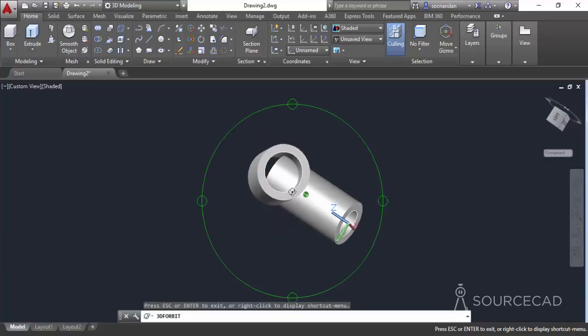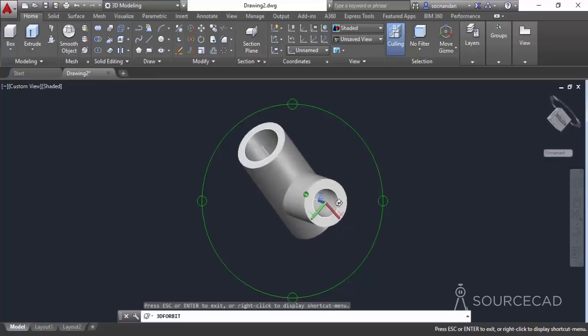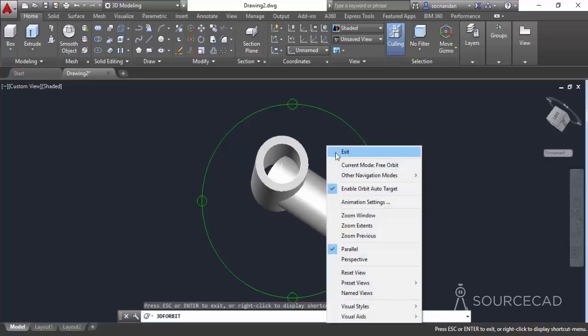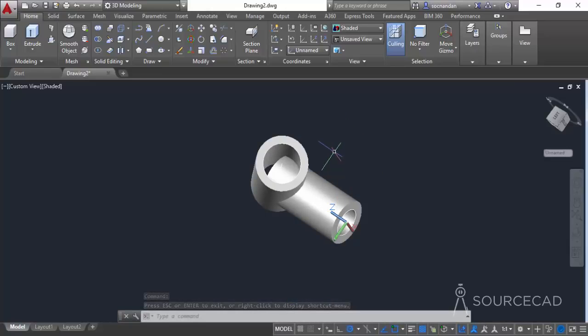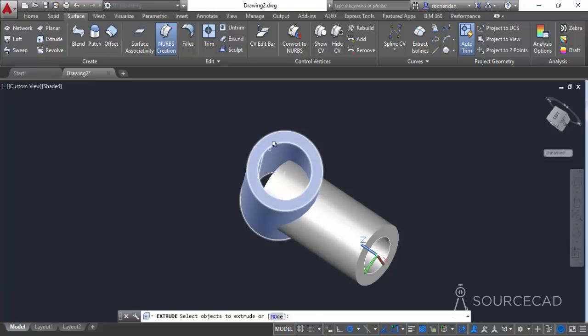Let's look inside these drawings, and here we have this portion which we don't need, and also we have here this closed portion that is not required. So we need to trim both of these sections. For trimming, we can use slice command, but before using slice, let's make two surfaces. So go to surface, select extrude and click on this internal circle. When you hover your cursor over this circle, you'll notice on this tooltip this overlapping square icon.